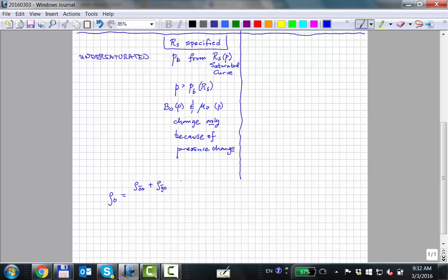We did a material balance, and we found out that this was the equation. If we want density of oil at pressure, we just go in, and these two numbers here are two constants. There's two of them. So we can get it if we know the BO, we know the RS.